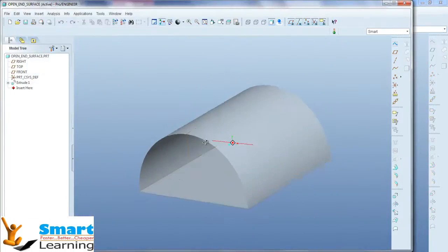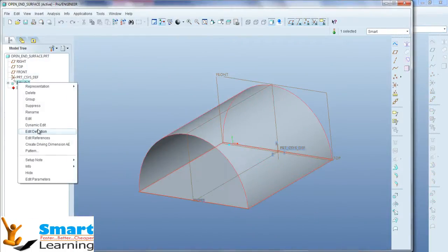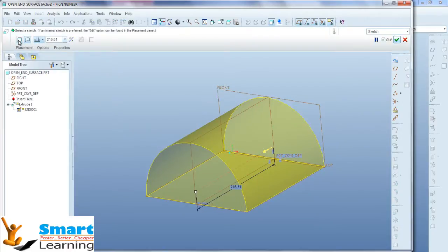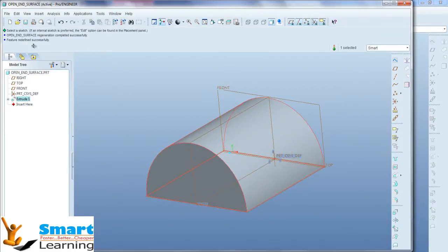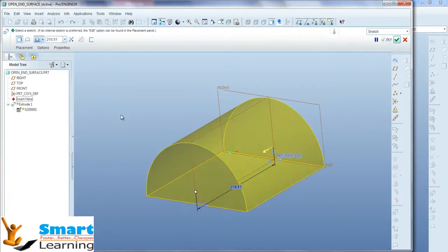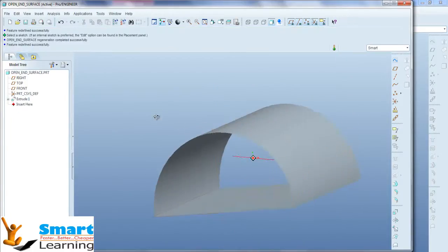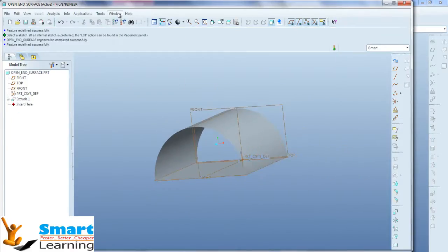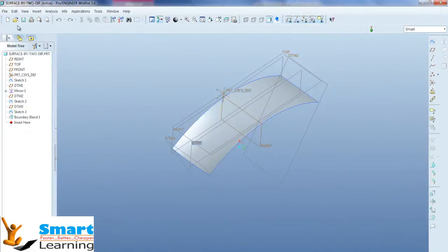So initially we'll start with the basic surfaces. If you see the extrude, within extrude you have a solid, which is the default solid. If you create the cross section, that may be open or closed, but if you click this surface option, then you will get this type of object, and this is valid for your revolve as well.